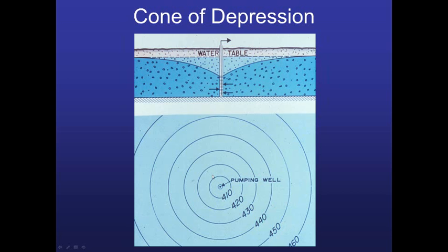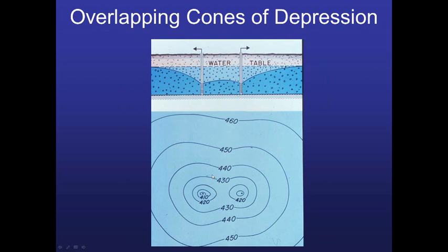And so as we move forward, if there's another well close by that's in the same cone of depression, all of a sudden you start seeing more drawdown, and the water level surface is lowered. I know we got a question the other day via email about a rural landowner whose well all of a sudden went dry, or at least their pump went dry.